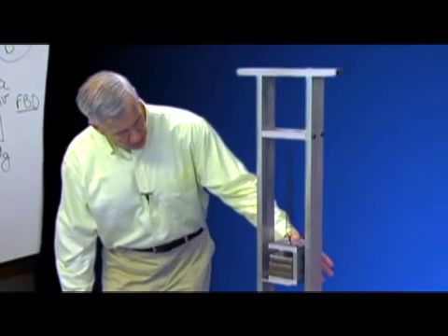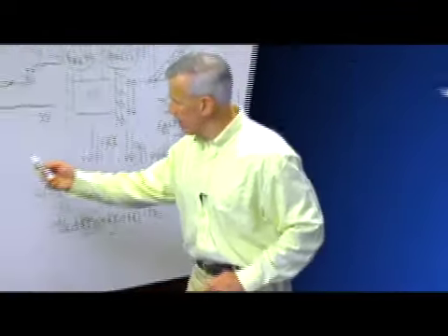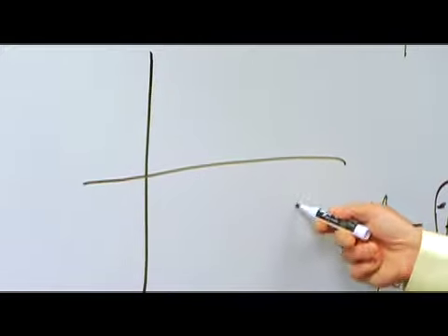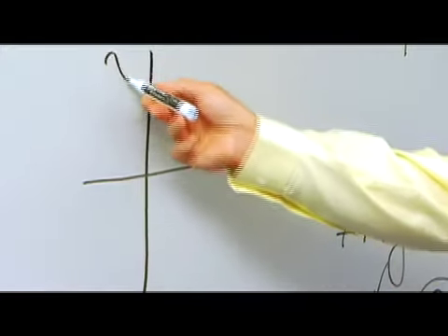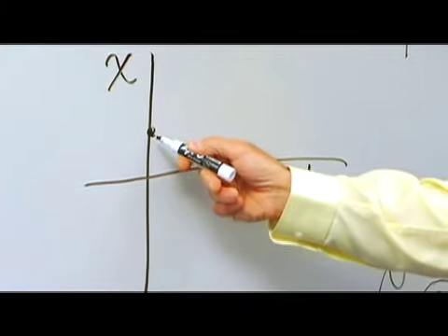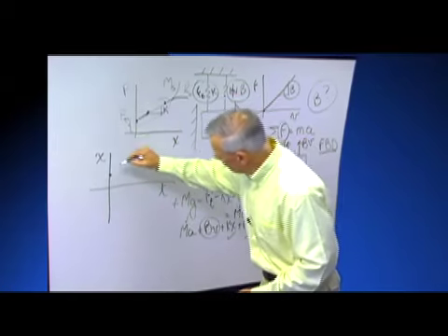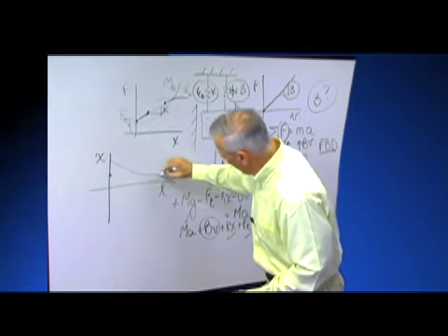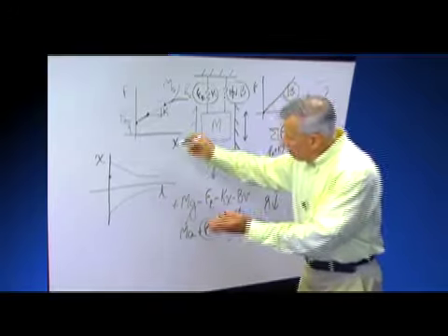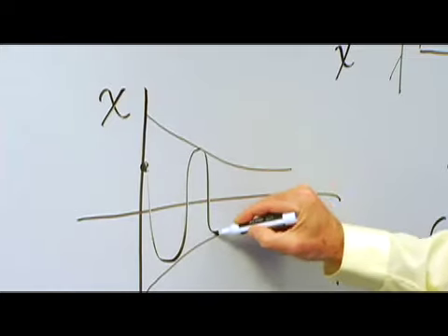Now, if I displace this in the positive x direction and release it, that trace, if I were to sketch it here, would look like this. If this is time and this is displacement, then if I started it at some positive x displacement, it would move in the negative direction and oscillate. And it would oscillate within some envelope, which I'm just going to sketch here. Now, this is not part of the response. This is just an envelope within which these oscillations take place.